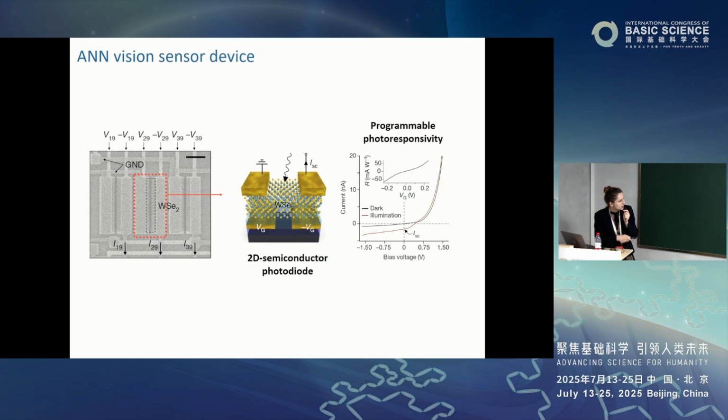And each subpixel is really a photodiode. What a photodiode is, it will produce current when you shine light onto it. So it's like a solar cell, but it will give you some current because it sees light. That's basically what a photodiode is. So in here, you can see a proof of concept that it did indeed produce some current.